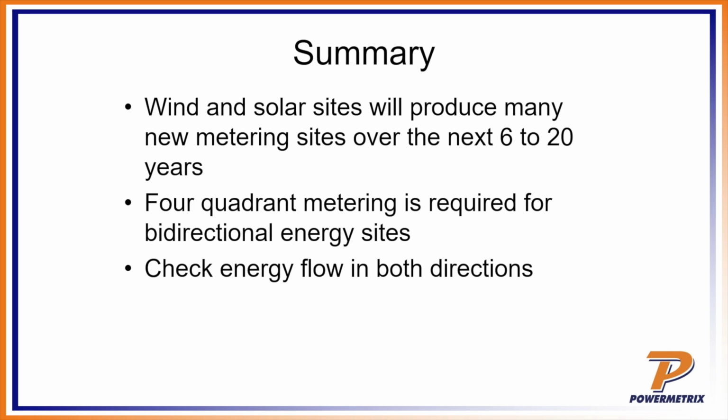So once again, in summary of the overall presentation, Four Quadrant metering is very important. It's going to become more important because we've got a lot more wind and solar sites being installed over the next 6 to 20 years. Four Quadrant energy metering is required for bidirectional energy sites. Be sure and always check your energy flow in both directions, folks. Make sure it's working both ways.